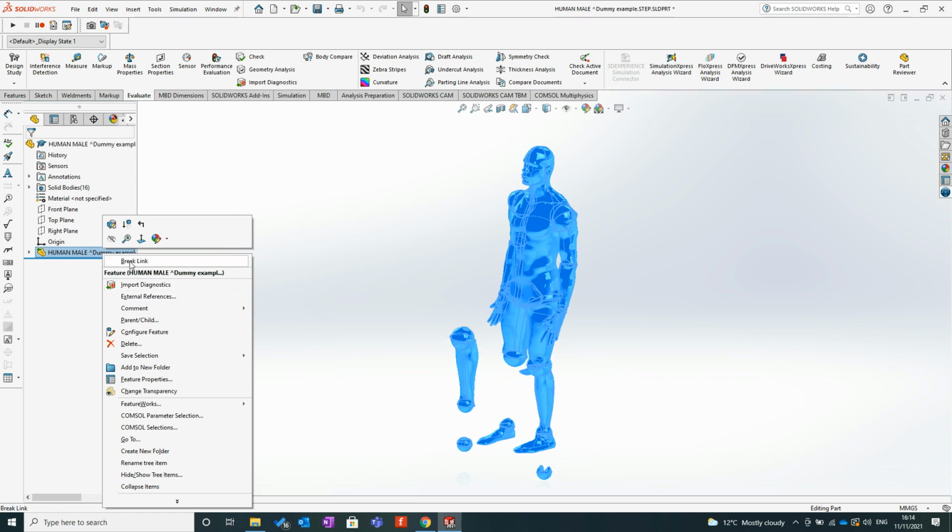So, see here we have break link. This is not just in steps, it is in a lot of geometric translation files. So this is step files, this is object files, and this is IGES files. STL files are just a cloud point of what that geometry was. So using that as something tangible and useful, you can get some softwares which will convert STL through to a solid base. Inventor, for example, is phenomenally good at doing that type of thing. But again, it's very chunky and a little bit of a pain.